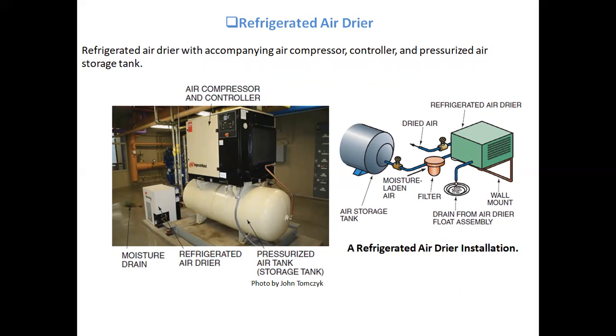So while compressing that air, the compressor also compresses that moisture, and if that carries over to the various pneumatic tools and other applications, that may lead to corrosion and other problems in that particular pneumatic machinery. So you need to remove moisture from the compressed air.